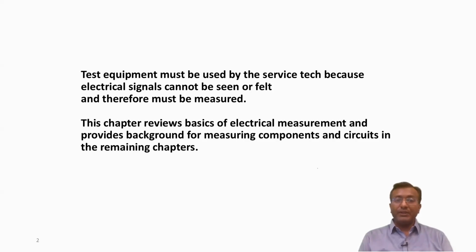As we know, these electrical signals are invisible, so to work with them, we have to rely on test equipment to diagnose these issues. Take a small example. If a car's headlights are not working, we can use a test light to check if power is reaching the headlight circuit. Without this tool, it could be very difficult for us to work on this system.